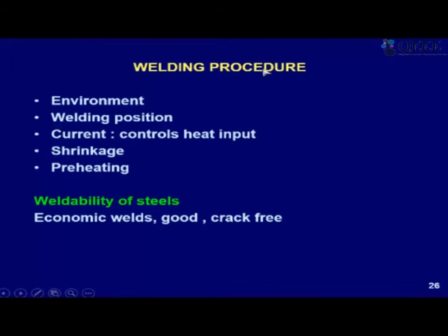So there are many welding procedures, and the important issue is how much heat or voltage you are applying, how much you are able to melt it, to what temperature you are able to heat that locally, the welding position, and then how the weld is going to cool.